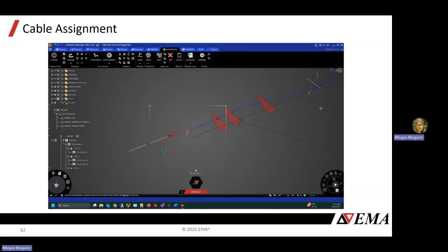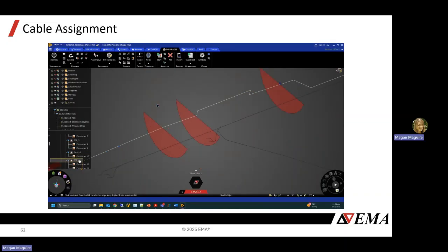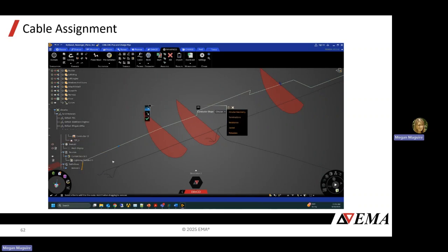Then you'll select your termination points, the beginning and the end, and also a bulkhead in the middle where we want the shield to connect. Once that shield is created, you can rename it to what you want, and then add some pins underneath it. In this case, we have a TSP, so we'll want 2 conductors. We'll start with 1 conductor definition, go to the library, and select a 24 gauge bare wire.